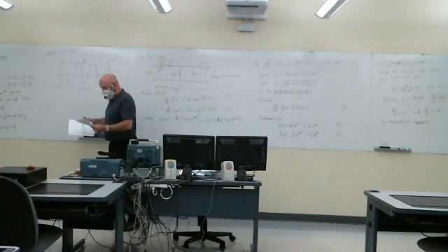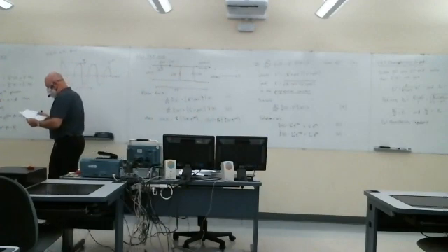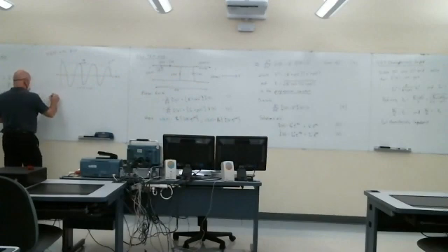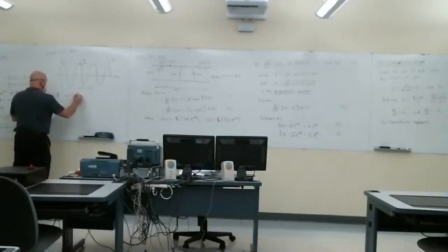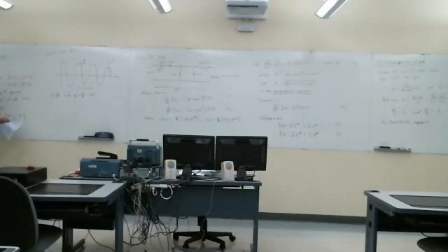So alpha is the attenuation constant, and beta is the phase propagation constant. And back from chapter 1, lambda and beta are related. Lambda is equal to 2π over β, and the propagation velocity is ω over β, or λ times f. Similarly, you can get an equation for the I+ term. It's going to be different. It's V0+ divided by the magnitude of the characteristic impedance, and then we'll have a phase angle term of our characteristic impedance. We'll look at that next time.